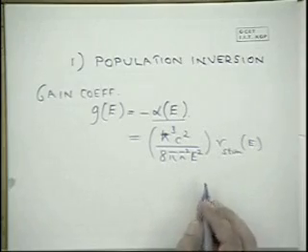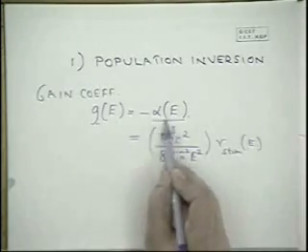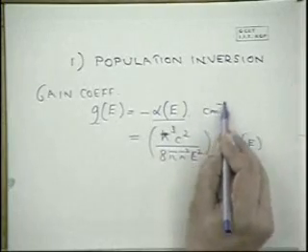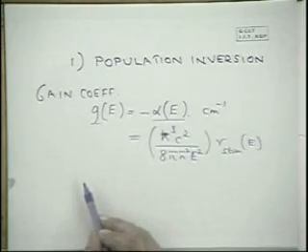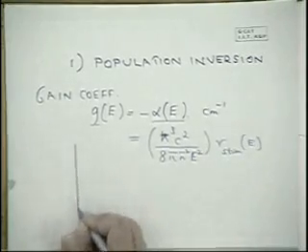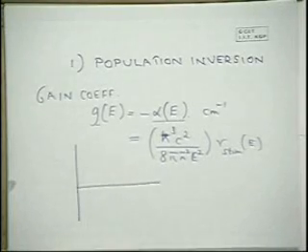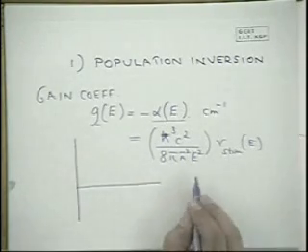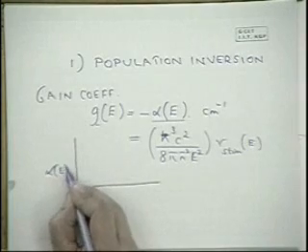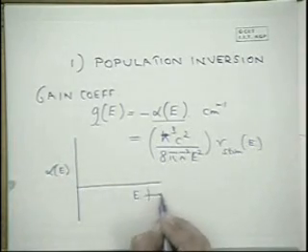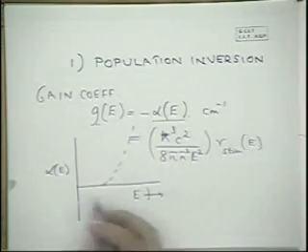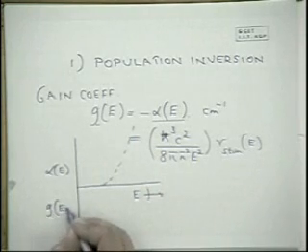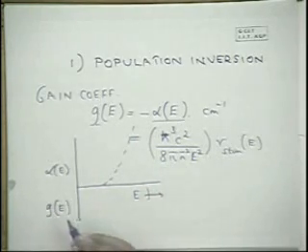And we see that the gain, alpha we know is the optical absorption, the units are centimeter inverse. So gain is the opposite of optical absorption. It is also measured in centimeter inverse, and we'll see that, for example, if you have a semiconductor which is a passive material, then if you plot alpha E against E, we know that depending upon the band gap of a semiconductor, we get some alphas like that. What we'll calculate later on is for different semiconductors.